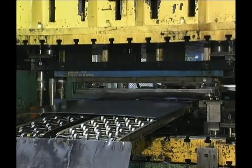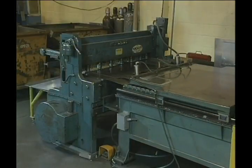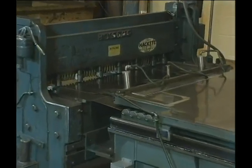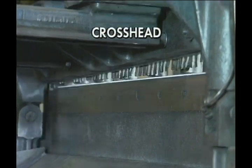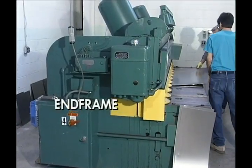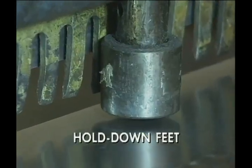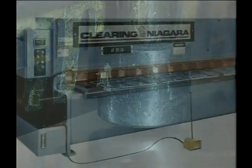Sheet metal shearing can be done within a shearing die and a stamping press, but is most often performed using a machine called a shear. A typical shear consists of a fixed lower blade mounted on the table or bed of the machine, and an upper blade secured onto a vertically movable crosshead. Other shear elements include the housing or end frame and the hold-down feet, which secure the sheet metal or plate stock to the table to prevent movement during the shearing operation.